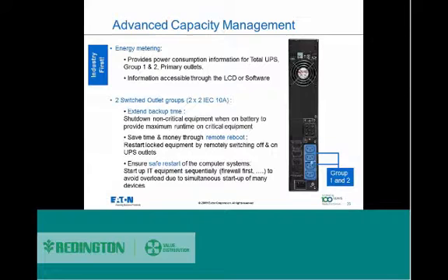Some of these sockets are also arranged in two groups, group 1 and group 2, and the load going through these sockets can be monitored separately on the display unit of the UPS, or else you have the option of remotely logging in and monitoring these devices as well.